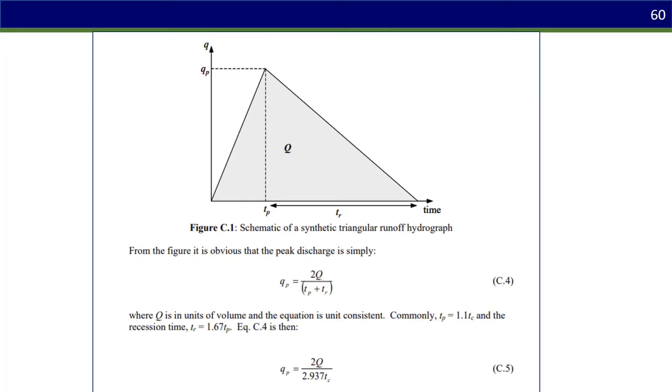This is a peak discharge hydrograph. It relies on something called the time of concentration. Right? So what we're calculating here is the time of concentration, the time it will take for the total volume of water to pass downstream to get to where the peak flow is at our culvert. These figures, equations, and documentation come from the Cornell culvert model documentation.